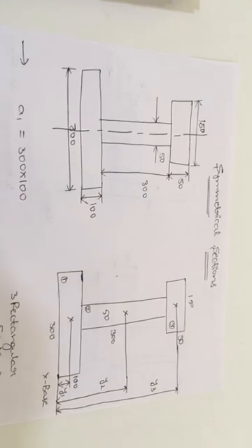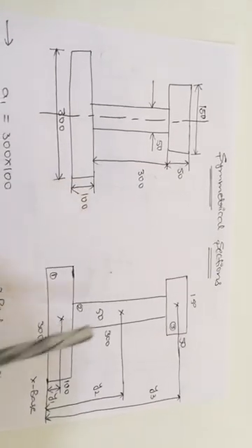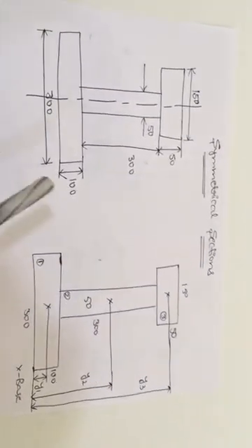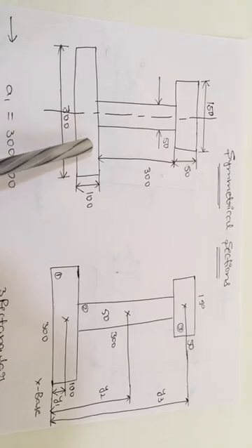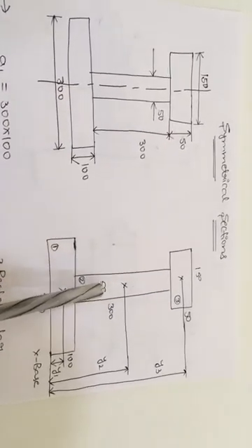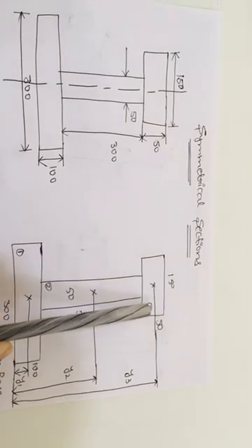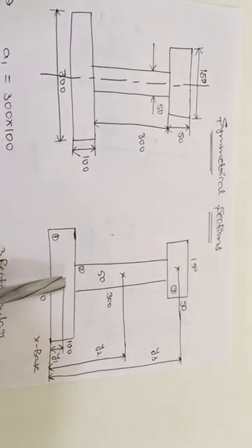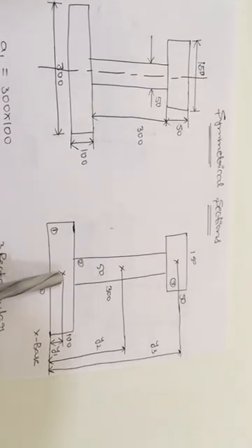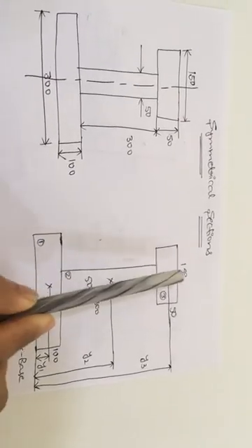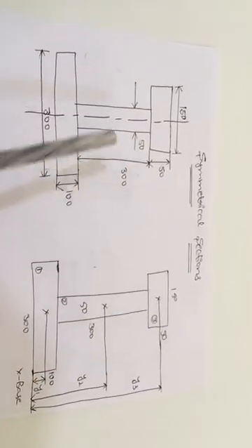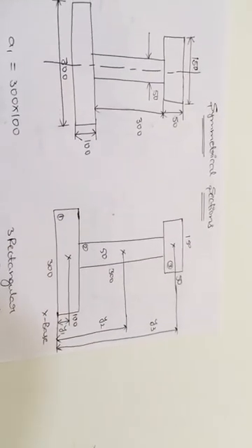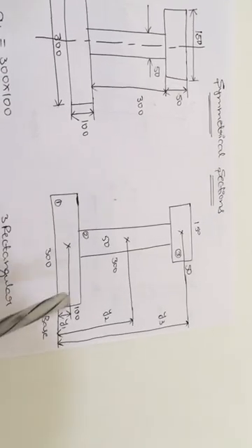Now for easy calculation purposes, you draw once again the original diagram. Now consider this section as the first section, next this section as the second section, next this section as the third section. Next locate one point, that point is nothing but the centroid point of the first section. So locate the centroid points for the individual sections. Next, as it is symmetrical about the y-axis, you will have only the y bar distance. So y distances with respect to the x-axis only. So project one x base.